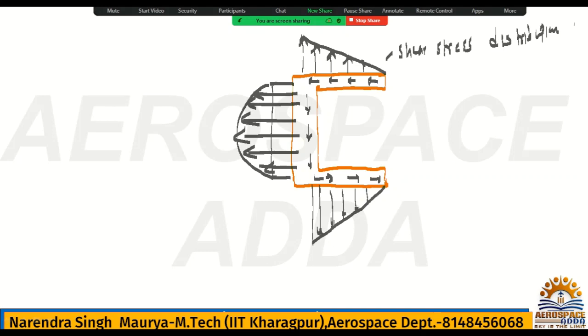Basically, where will you get more shear stress? In the web. This is called the web, and we also need to remember this is called the flange. For single marks they can ask where the maximum shear stress occurs in a C channel. You have to say in the web. So this is the tau max. Maximum shear stress you will get in the web portion.